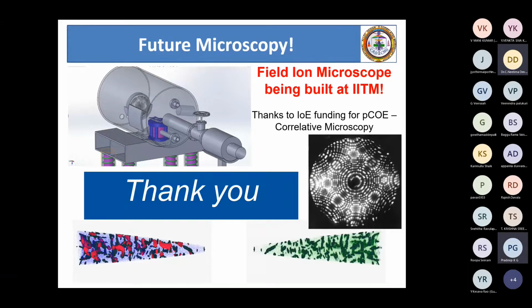Correct. We have added silicon intentionally. Silicon is only for accelerating alumina formation. Is there any specific reason behind that addition of silicon? So we initially produced a coating without silicon, and we were still able to get alumina on oxidation. But the thickness of the alumina was not sufficient to claim that the crack is fully covered by alumina. So therefore, we wanted to accelerate the process of alumina formation.